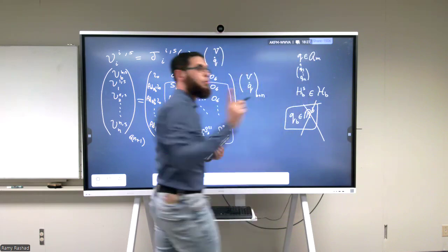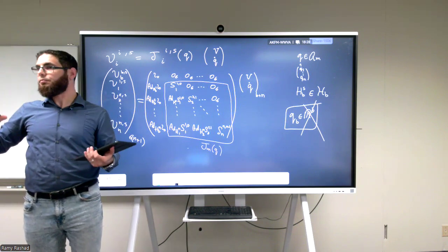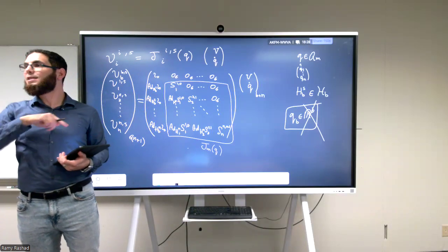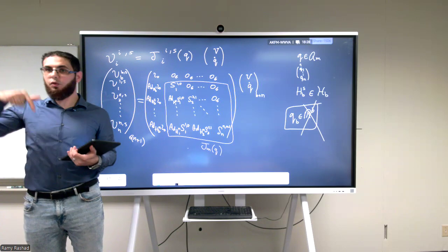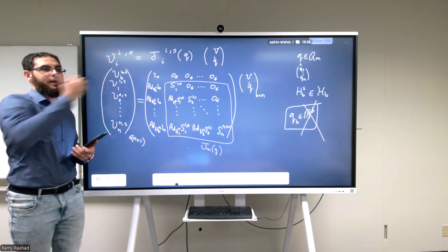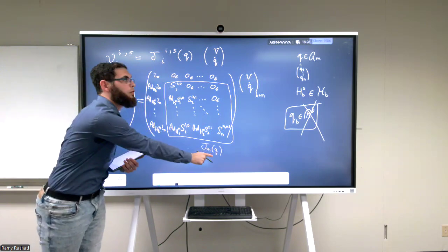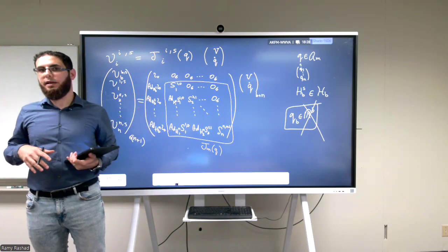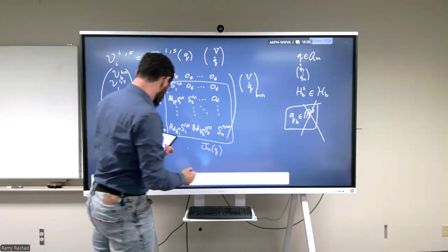You see, even though the base is moving, this is very strong. Even though the base is moving and doing all sorts of stuff, its motion doesn't affect the Jacobian at all. We don't see the V inside of the Jacobian. That's one thing. What's even better than that, the configuration, which is HB with respect to S, also doesn't appear here at all. So this Jacobian is only a function of the Q of the manipulator, not the Q and the H of the base. And what you see here is that we can rewrite this whole thing as something.